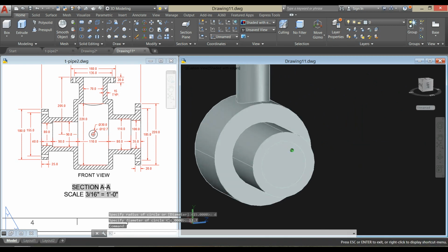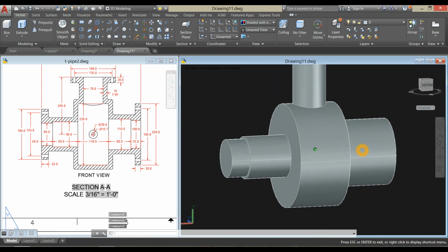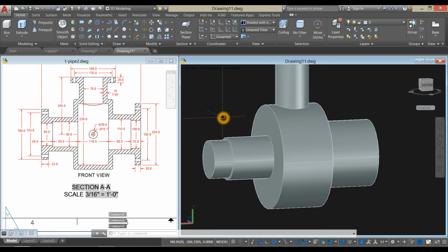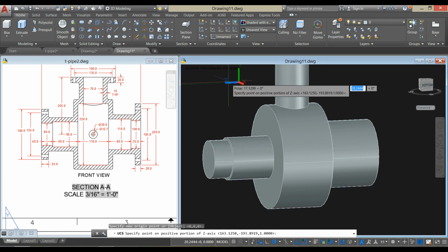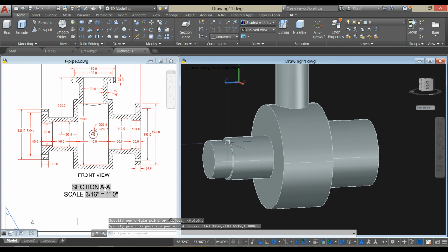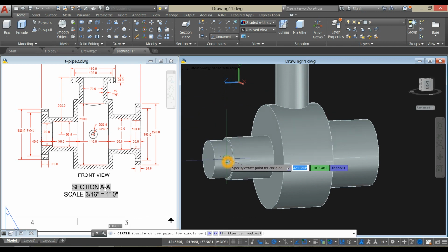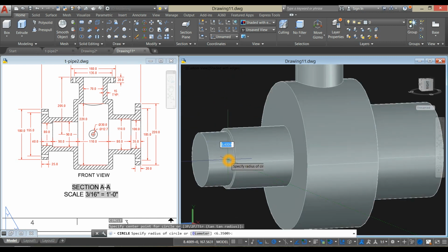Alright, let's go back to applying walls to the bore. So change the direction again of your Z and parallel to the direction of these cylinders. So C for circle. Click that center here. Type D for diameter option and add 30 to the diameter.